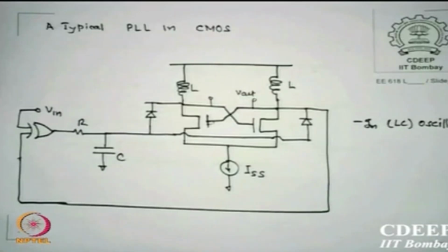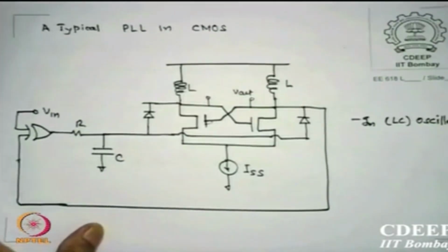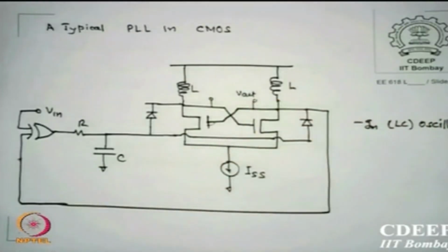So this is essentially why I say PLLs are very crucial for real life requirements, because you want to hold this frequency to a constant value before you use it in particularly RF applications, where the image is very strong. It will pass through to the digital side and that may create huge noise. Your capacitor requirement for the A to D converter will be very large. It is very difficult to maintain large capacitances on chip, and therefore you will always try to reduce the frequency from the higher ones, and you do not want images to move through. So no DC signal should go out. It is very important that it settles to a frequency exactly.